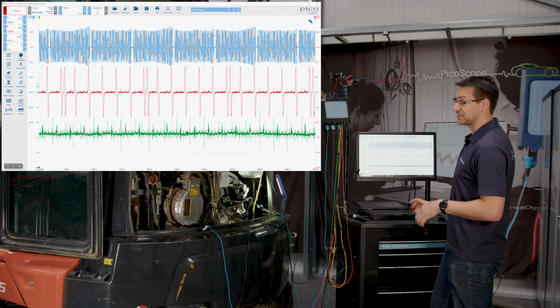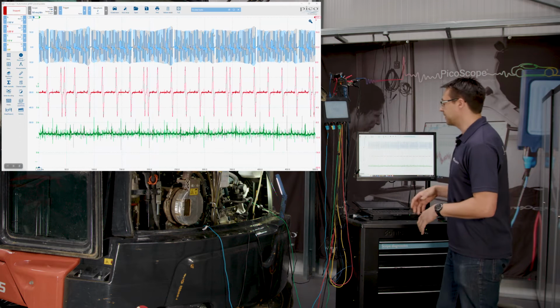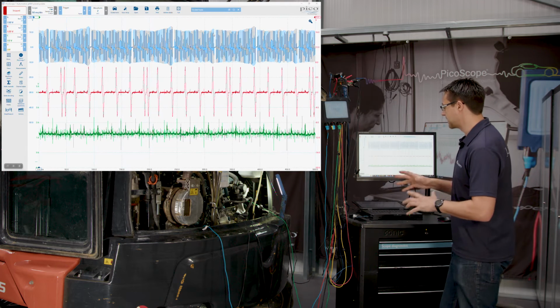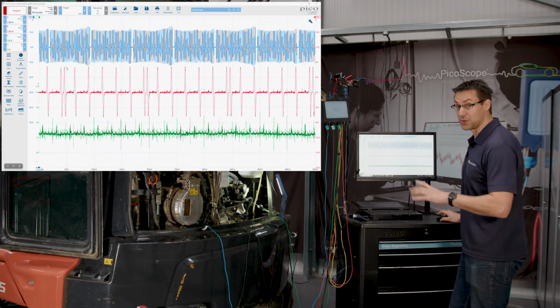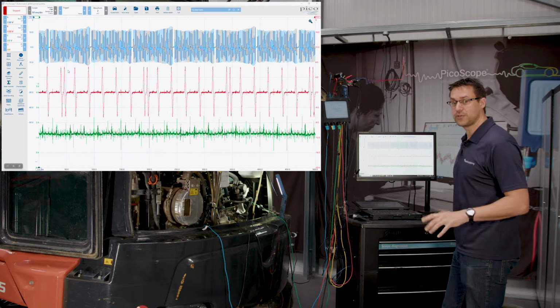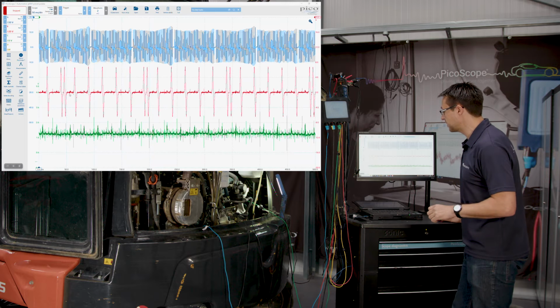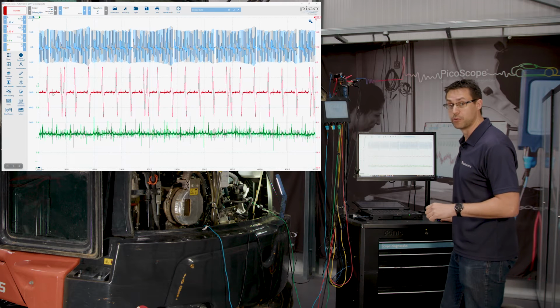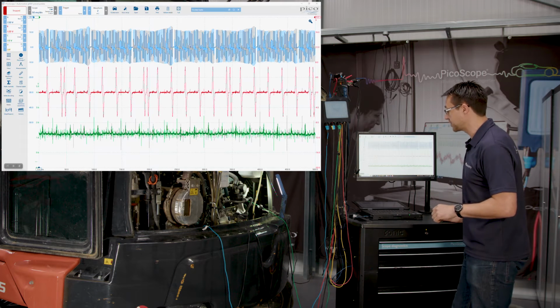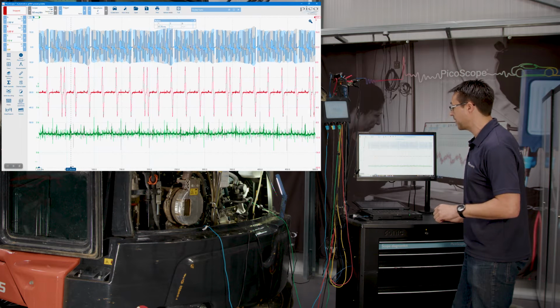Now this example actually has used the camshaft sensor as our cylinder identifier. Quick little tip: for the majority of machinery that I have seen, cylinder 1 occurs after the double pulse on the camshaft sensor. So in this case, cylinder 1 fires round about here.